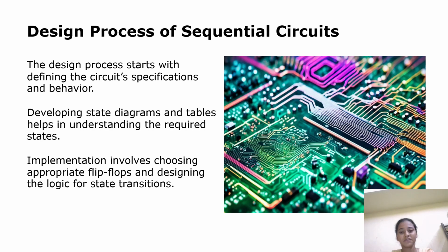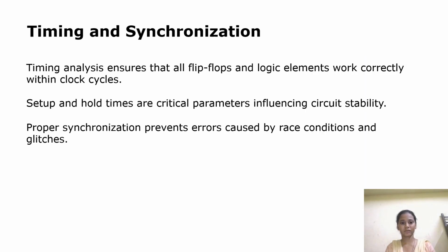Design process of sequential circuits. The design process starts with defining the circuit's specification and behavior. Developing state diagrams and tables helps in understanding the required states. The implementation involves choosing appropriate flip-flops and designing the logic for the state transitions.